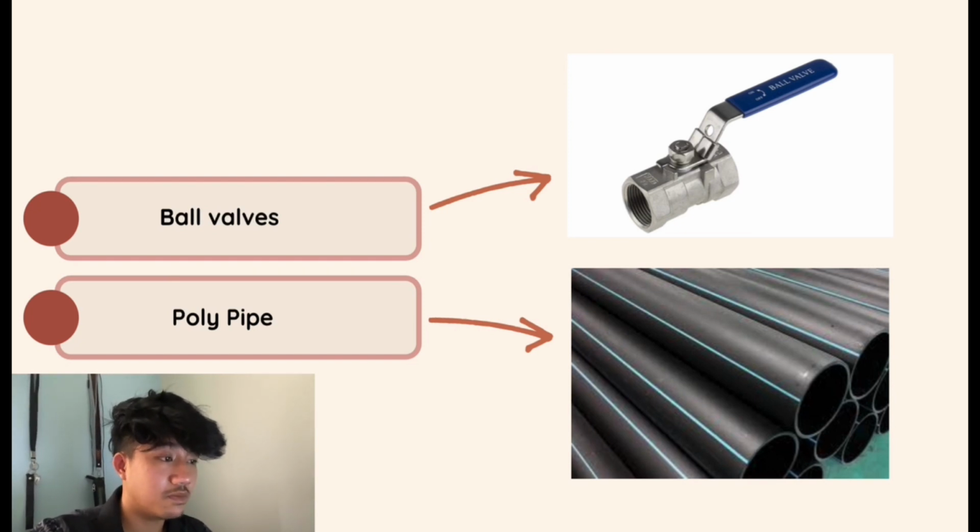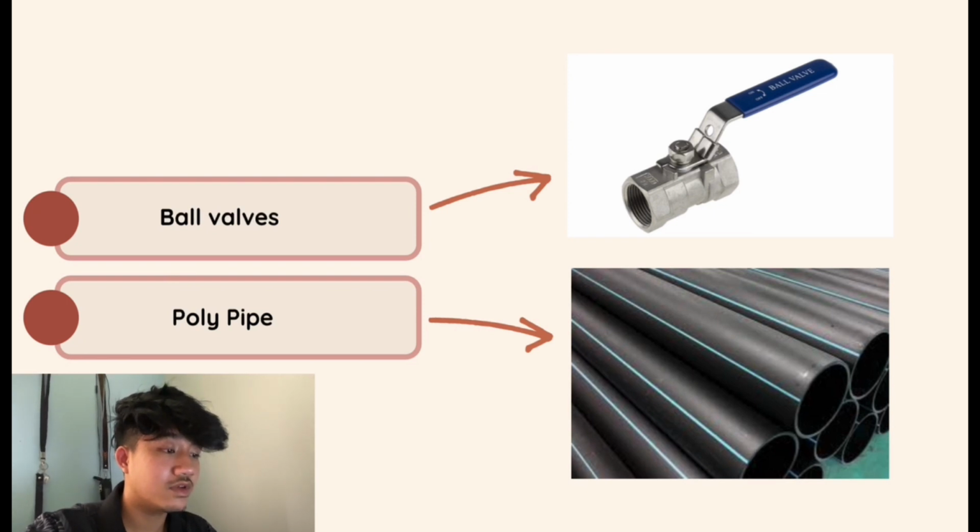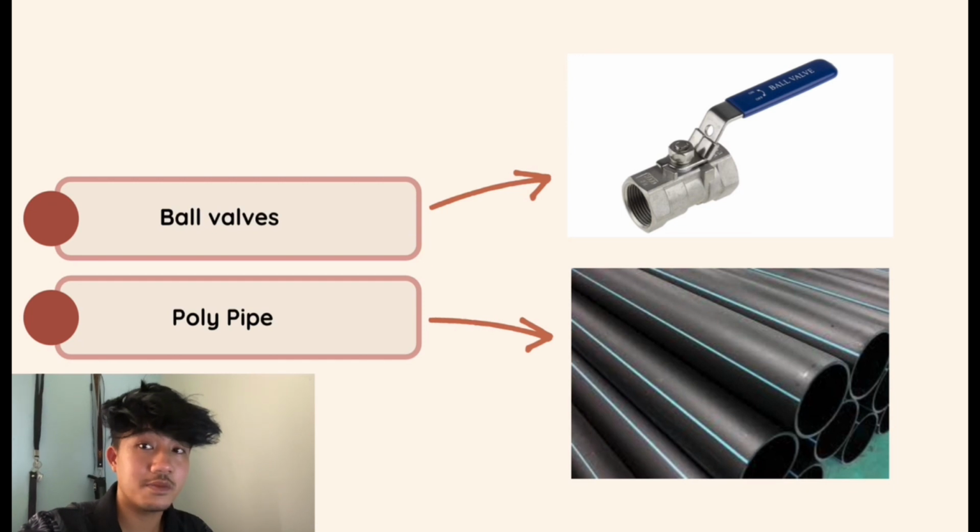Next, for the poly pipe HDPE, involving our water delivery system, we use this poly pipe HDPE as the most ideal among our discussion with our group members. We choose this pipe because it is leak-free fused, which is one of the advantages. It also can handle significant pressure, and it does not rust and corrode, which will minimize our maintenance for our water delivery system.